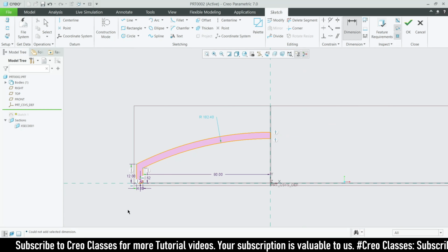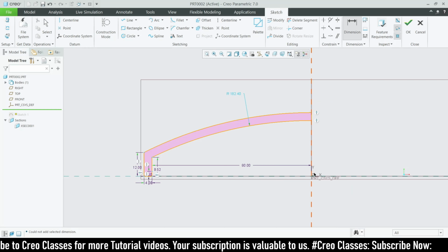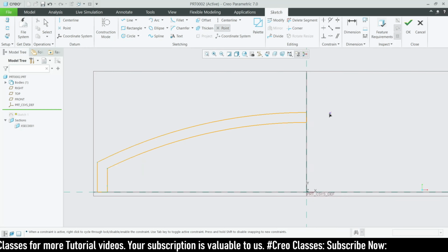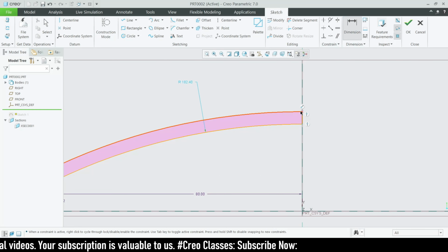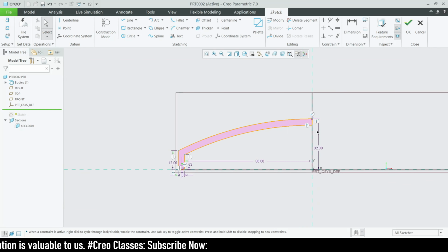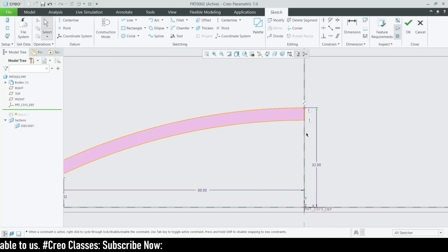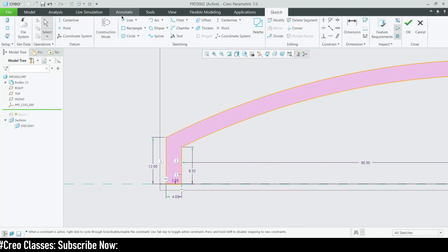After creating this, first of all place a point here. I forgot to show this height. I think this will be 32, yeah, 32. So place this single point at a height of 32. After placing that point, directly select this line, this line.